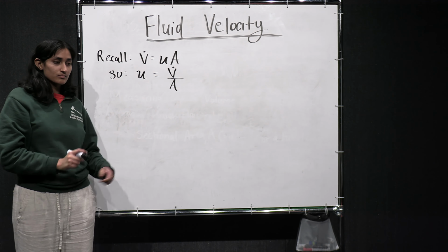Yeah, probably the easiest way would be to do total volume that gets distributed. So I know that I can measure the diameter of the pipe or the tube, right? Use that to fill up my container in a given time, and find the volumetric flow rate by backing that out, and then from there just divide by the area to get the velocity of the flow.